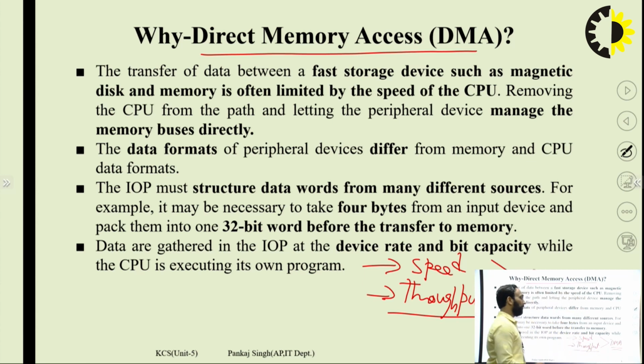Okay, how does it work? It overcomes the communication time between IO devices and memory by excluding the processor, using a DMA control mechanism, in which the processor is involved once to take the request from the IO devices, and after that the control is handed over to the DMA controller, and the DMA controller will work as a mini processor relevant to the input output operations. So why do we need DMA?